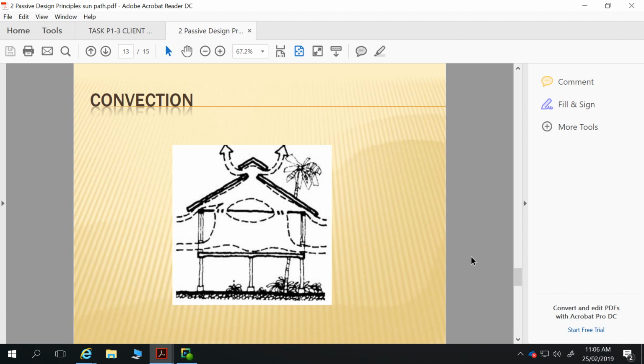Prior to that, it was about how you make do with the building and the climate. That sort of design, unfortunately, doesn't meet the energy rating assessment criteria very well, and also doesn't meet the deemed-to-satisfy requirements within the NCC, because the energy rating assessment is very much about encapsulating a house, stopping uncontrolled drafts, so that climate can be controlled very easily.